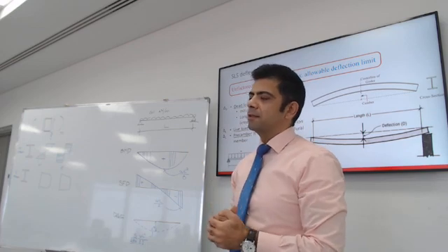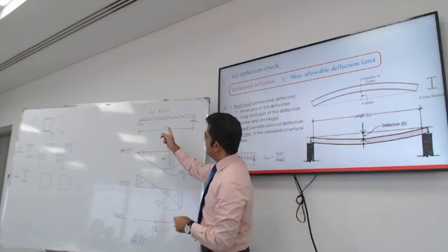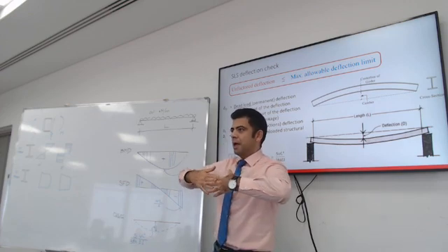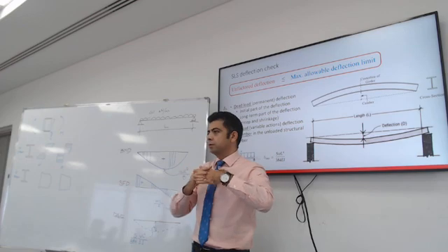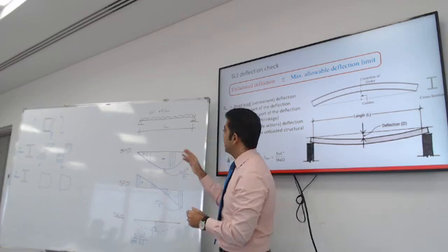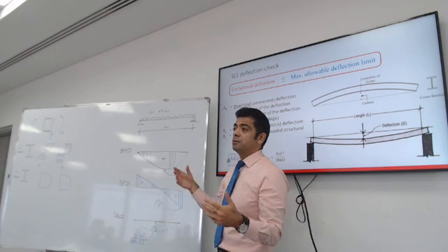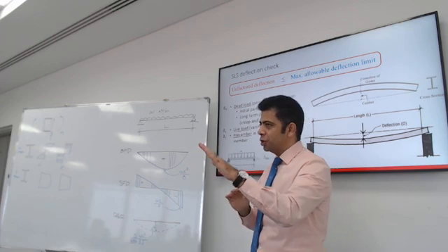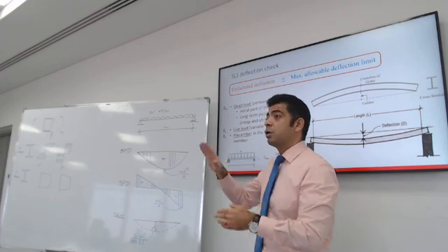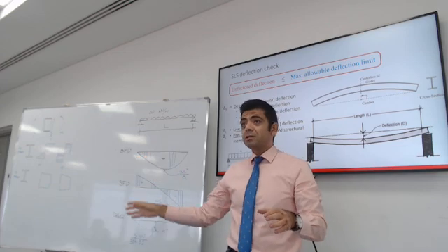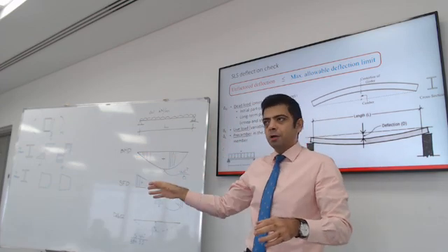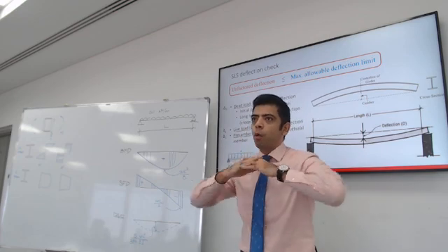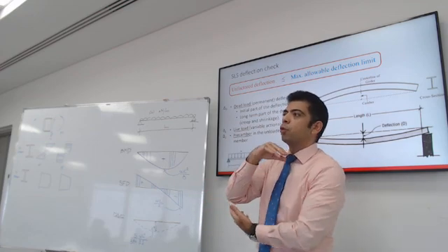That's a great question. I would say if the beam has a roller on one end, it doesn't matter. The deflection will straighten up, and that side is free to move. You might run into issues if this is a statically indeterminate beam, a continuous beam. If the camber is minimal, it shouldn't change the distribution of the load. If this was an arch girder, a beam that has a significant curvature, absolutely, that will make a difference in the reactions, because the arch wants to open up at the bottom, so that would affect your reactions.